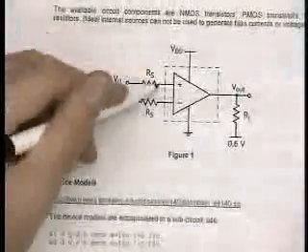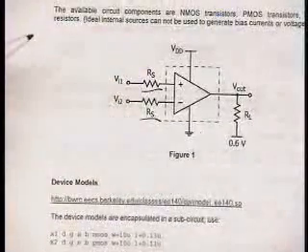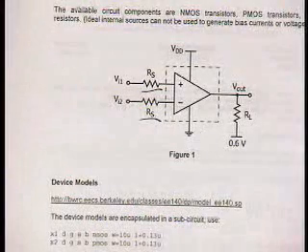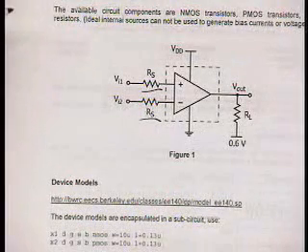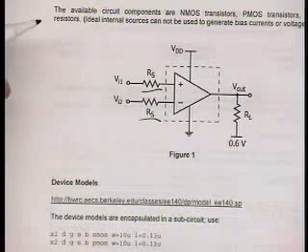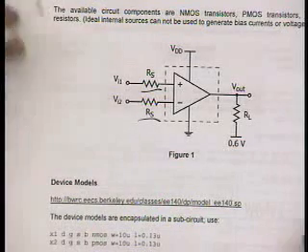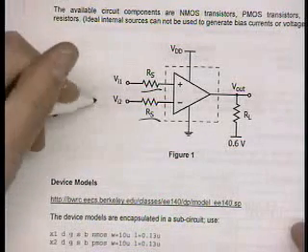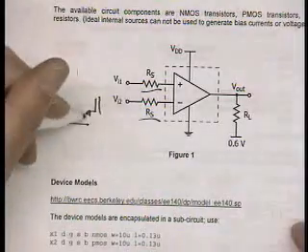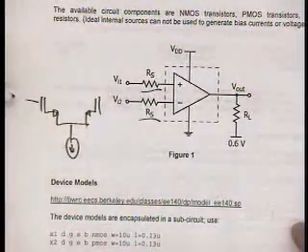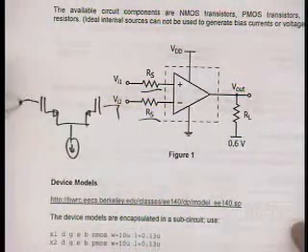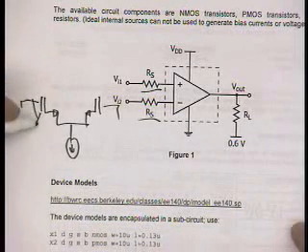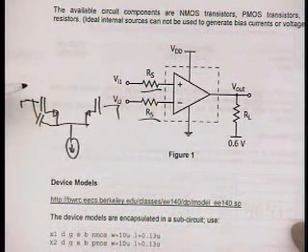RS, which is something a little different, something new. Now there's a source resistance on each driving side, and those are each 500 ohms. And the reason for that is because we want there to be a pole at the input. Chances are your input structure will look like either an NMOS or a PMOS diff pair, and if these are driven by ideal voltage sources, it doesn't matter what capacitance this is, right?